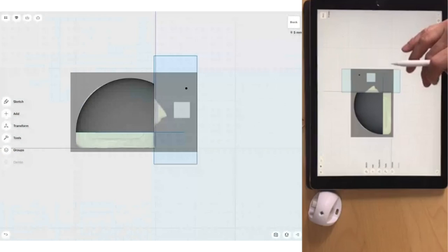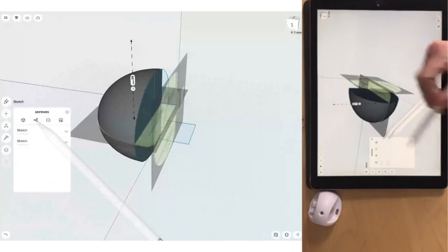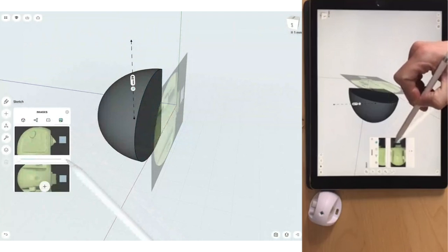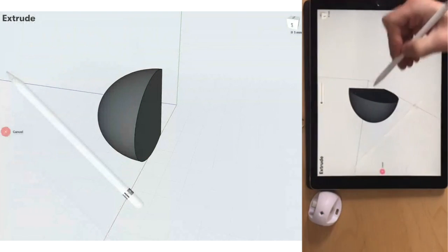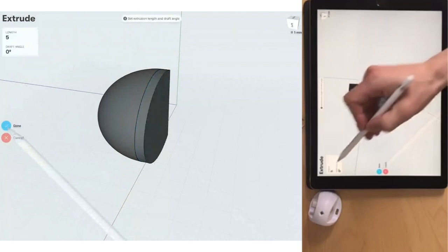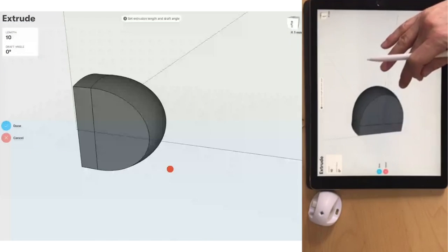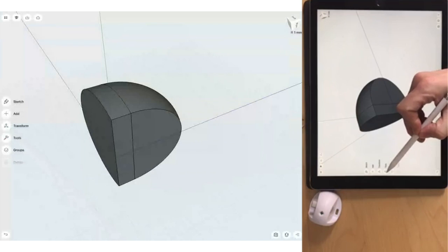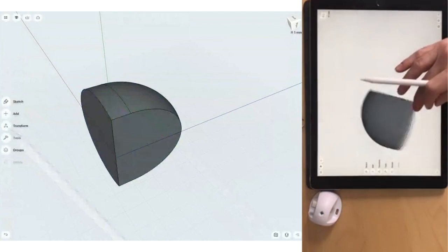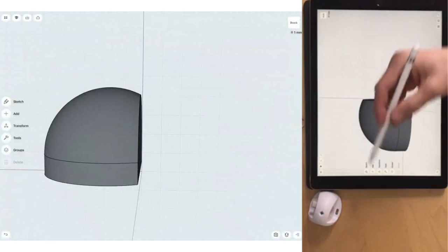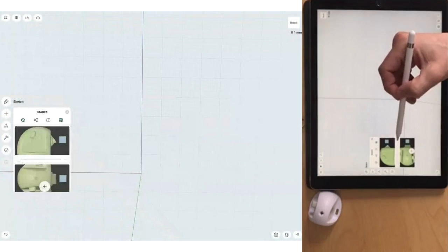There. So how do we do the bottom part? Well, as I said, this is just a flat extrusion. I turn all these off for the moment, and I go to extrude, select the bottom face. That was 10 millimeters down because I moved it up 10 millimeters. And we have to join these two together. There. Awesome. Okay. We're making good progress. Let's take a look at this.